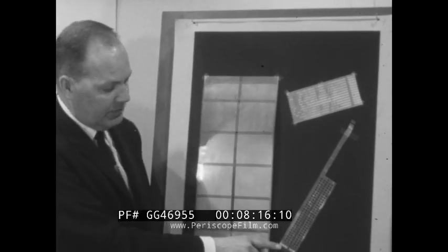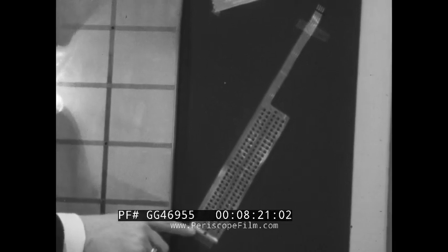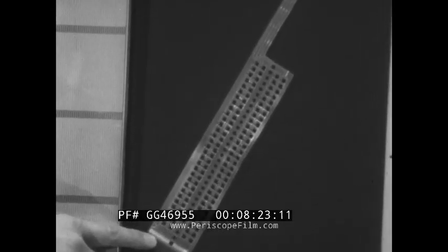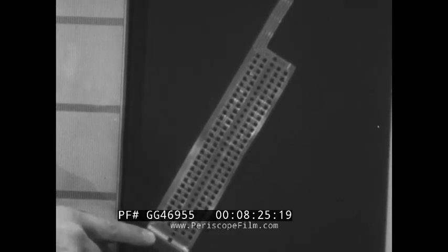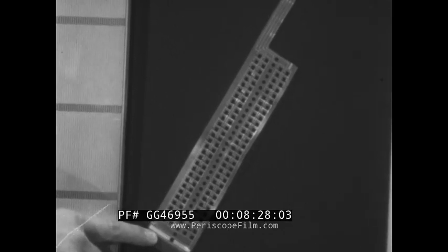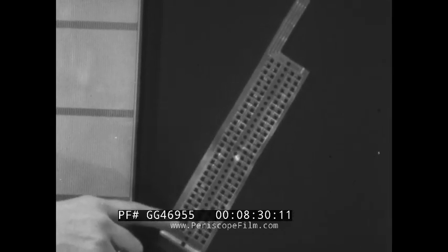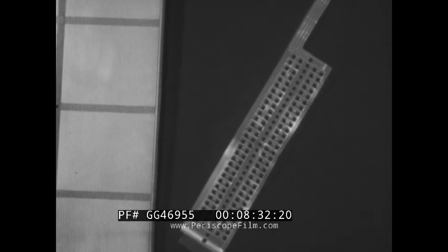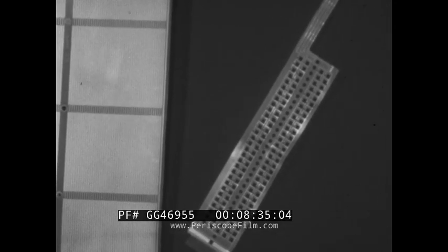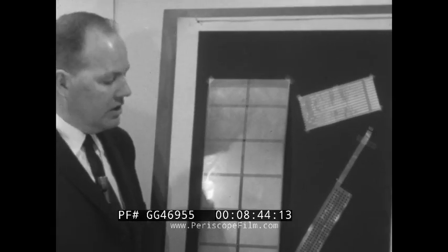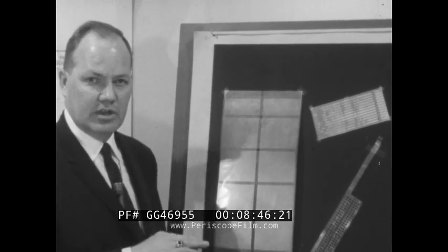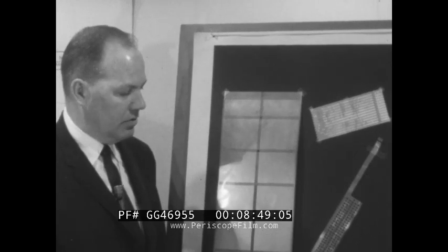In the case of the Model 40, the engineers developed what we call a transformer read-only storage. I'm sure most of you are familiar with transformer action. You induce a current in a primary coil. This develops a field around the coil, and if you have a core running through that, you can then develop a secondary pulse in a secondary winding. And here again, if we have the presence of a transformer pulse, we have a 1 bit. If we don't have the impulse, then we have a 0 bit. So we have again the 0-1 binary bit pattern required.